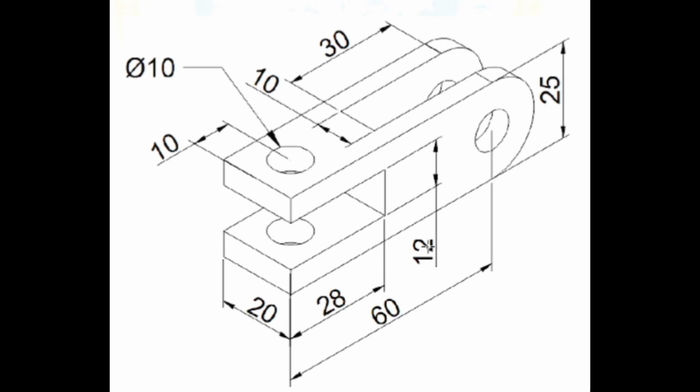So question number 4, it consists of boxes as well as cylinders. Okay, so here it is made up of multiple boxes and cylinders. We have to construct one by one using primitives available in the AutoCAD as well as Boolean operations.